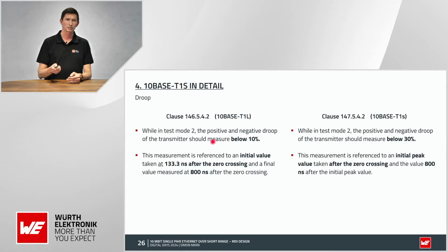So in 10BASE-T1L, you are measuring the initial value, the zero crossing, and after the zero crossing at 133 nanoseconds, and after 800 nanoseconds after the zero crossing, you measure the values, and if the droop is then below 10%, this is a good circuit, so it is according to standard.